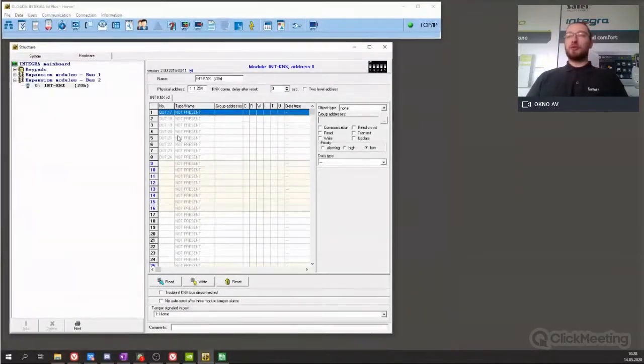For example, I want to use 32 outputs, so I need to set DIP switches, I think 6 and 8 up, just as the information. So every value higher, so 6 is 1, 7 is 2, and 8 is 3. Every value higher, so you can increase it, then you have an additional 8 assigned to this module.